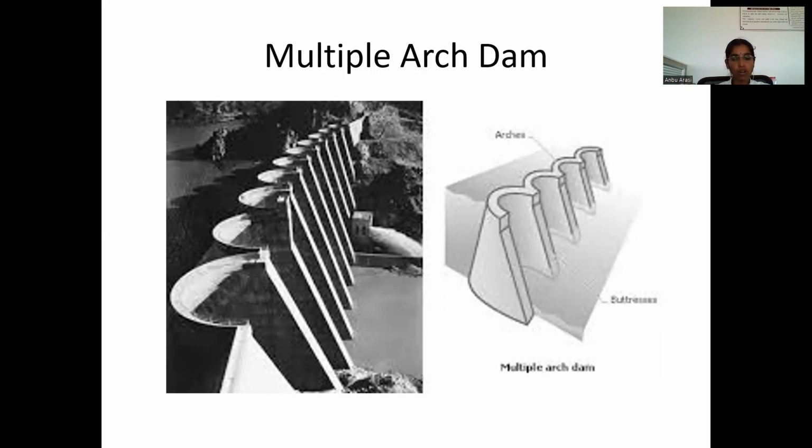The chief geological criterion is that the rock must be absolutely reliable to bear 2 to 3 megapascal or more without any appreciable settlement, less than 8 mm. There is some saving in concrete compared with buttress dams. In respect of uplift, corrosion, and economy, the two types are very similar.